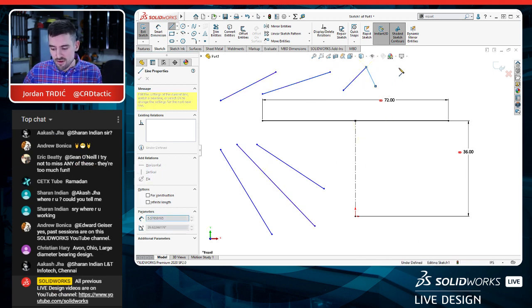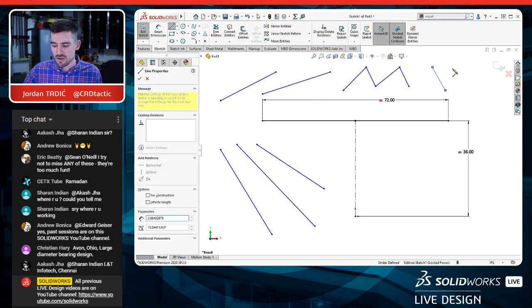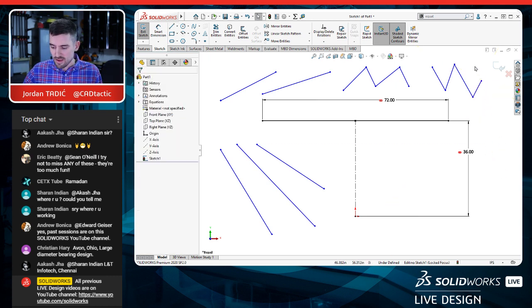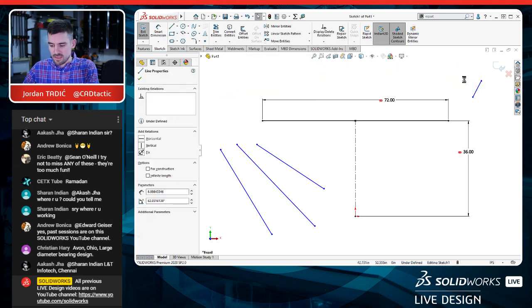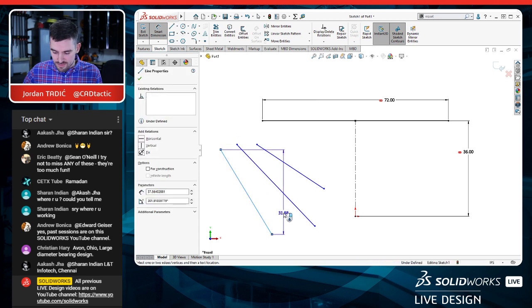Typically what happens is you click, click, click, click, and it draws a bunch of chained entities. You could still do another keyboard shortcut, or I guess a mouse click shortcut. If I don't want to draw this final line, this chained entity, just double click. And then you could start a new chained line of entities and then double click again. So there's a few tips. I am really dirtying up my working environment, so let me delete all that. And then let's add some dimensions here.